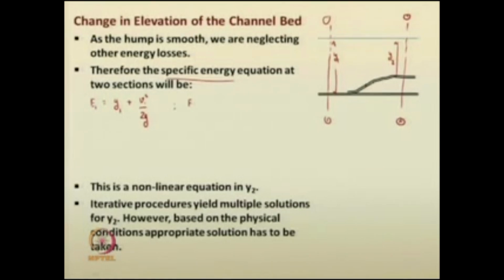Similarly, the specific energy at section 2 is the depth of flow y2 plus v2 squared by 2g. We do not know the elevation, whether it is here or here, y2, that has to be analyzed.